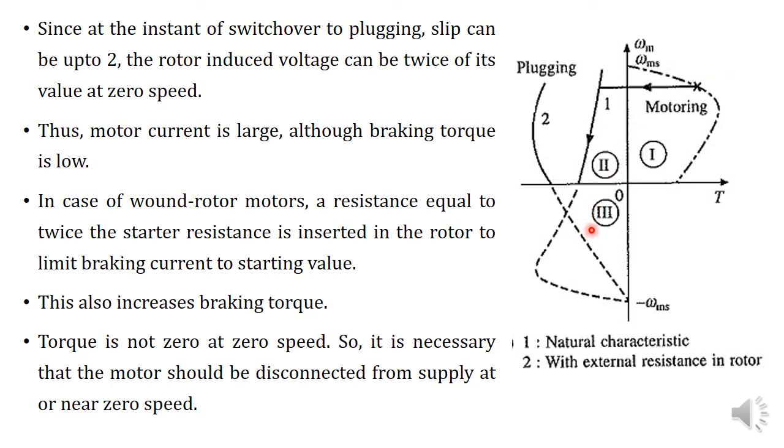In the third quadrant, reverse motoring is happening, so the curve will be very similar to that of the first quadrant, but reversed. So the characteristics during plugging will be an extension of the characteristics of the third quadrant.